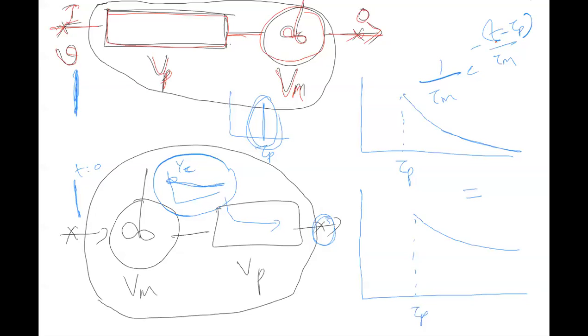So last graph somebody is asking to explain, because see, I put, let's say, at time t equal to 0. This is my RTD. Then this is how the RTD is spread by CSTR. Now this entire graph goes to the PFR. It doesn't change anything, no. PFR, whatever comes in goes out of the PFR as it is, only time is delayed by tau p minutes.